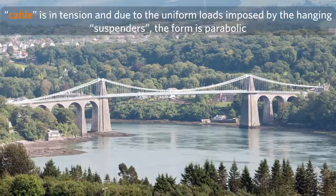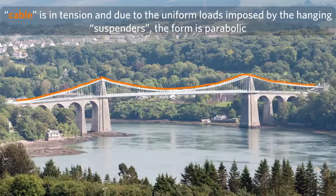Next, let's look at the cable. The cable goes from anchor to tower to the next tower to the next anchor, and it is in tension due to the uniform loads imposed by the hanging suspenders. The suspenders are the vertical elements that suspend or support the deck. The form of that cable is parabolic. I'm going to do a brief demonstration to show you the shape that these cables take when loaded, and it'll give you a better sense for why the form of the suspension bridge cable is parabolic.